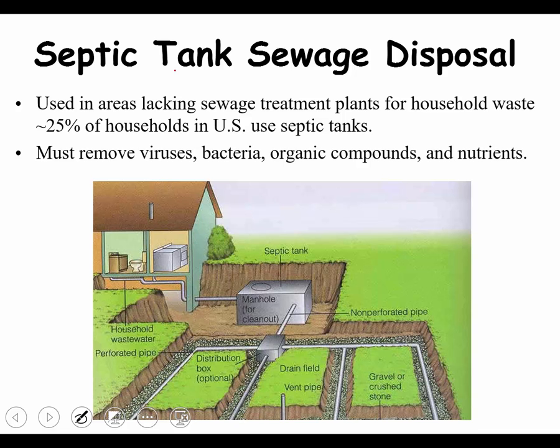And the way they work is basically the water comes into a large holding tank where the solids precipitate out or drop out, and then there's a perforated tube that comes out, and then the liquid portion is drained out through a series of slotted PVC tubes, and the idea is that it's dispersed and then it does gradually drain into the groundwater, but the intent is that through filtration and through distance it cleans itself up.